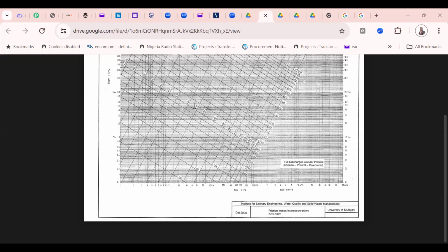What does 46, between 40 and 50, signify? It is the flow in liters per second, the water demand for Wuse, based on the population equivalent of 46.3. Okay, in fact, if you want, make it 50 and give another safety factor to it. The more the better. So we go to 50 and go up, and look for where 5 is. You see that it's falling between 200 and 250. Somebody confirm: the pipe size is between 200 and 250.